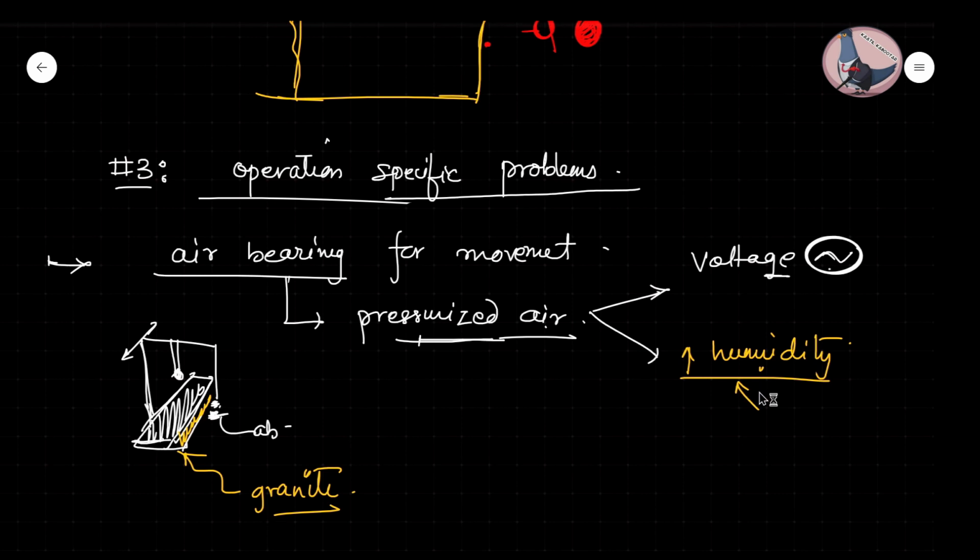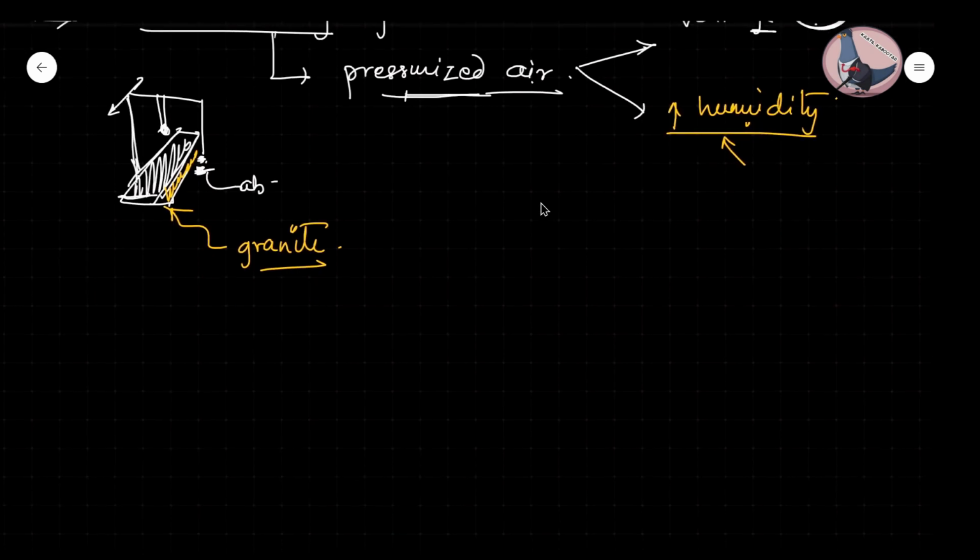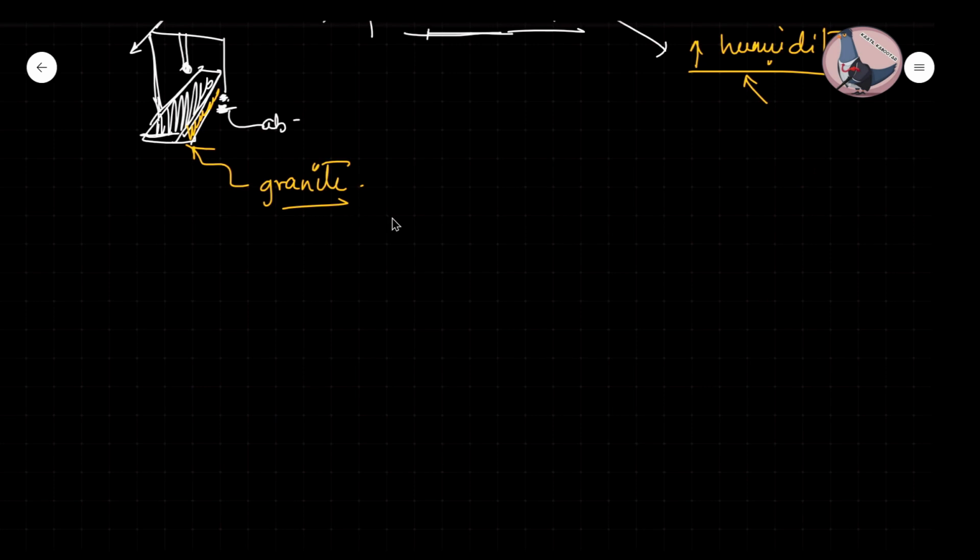Okay, now such types of things are also there. Then what else? Now, one thing is called the mass of the workpiece. You can very well understand that the mass of the workpiece can cause deformation in the structure itself. So the problem will come. Then there can be deviation in measurement due to deformation in the job itself.